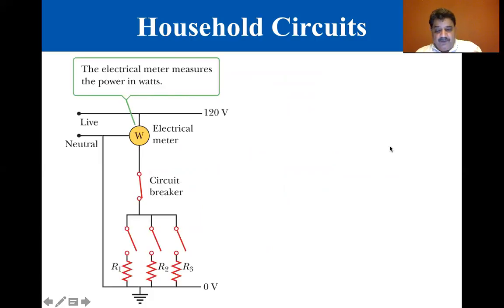When wiring, both the wire and the circuit breaker are carefully selected to meet the current demands of a circuit. If the circuit is to carry currents as large as 30 amps, a heavy-duty wire and an appropriate circuit breaker must be used. Household circuits that are normally used to power lamps and small appliances often require only 20 amps. Each circuit has its own circuit breaker to accommodate its maximum safe load.